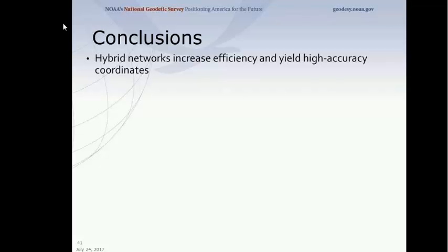And it kind of falls in line with how I've always done surveys when I used to work for the BLM. When I worked for the BLM, our typical conventional approach was, when we start a survey, we'd use OPUS to establish control at a few stations. And in this example, I'm proposing that we take that a step further and use OPUS Projects. And then you fill in and densify your network using RTK. And that's kind of how we used to do that in BLM. And you can see what accuracies can be achieved. And next.